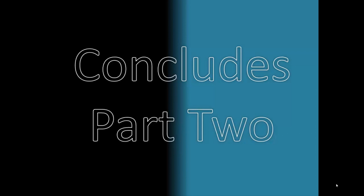Probably one of the best examples of an add-on instruction is where in ladder logic you want to do something with structured text or with function block diagrams, but you don't want to create a separate routine. Well, in a way, when you create a class of objects, we'll say that you want to create an add-on instruction called tank temperature, and in that add-on instruction it's function block diagram, which is the good language to use for controlling the temperature of a tank. That instruction can be included in ladder logic. So this got to be kind of a complex application.